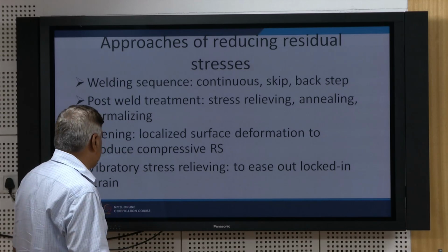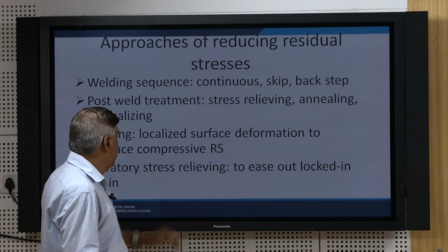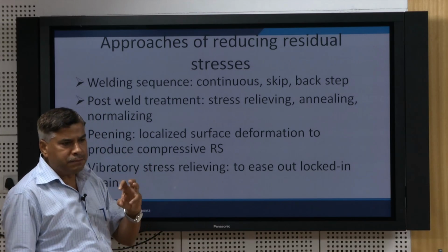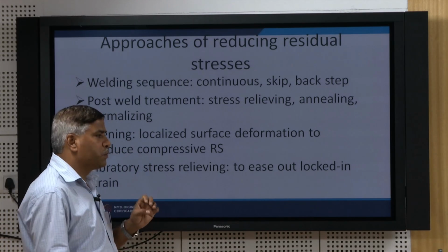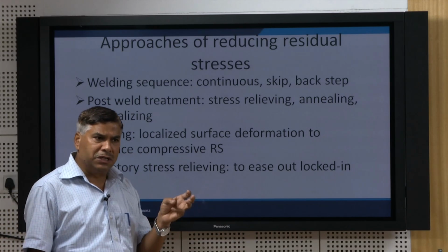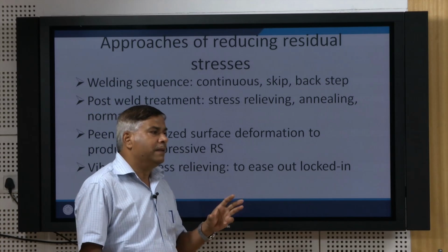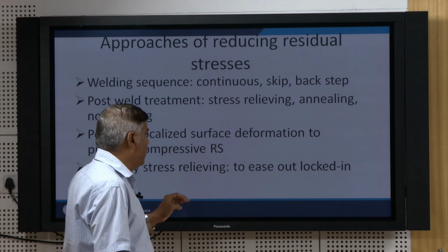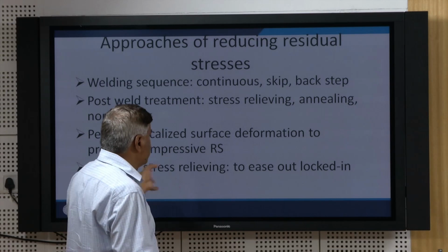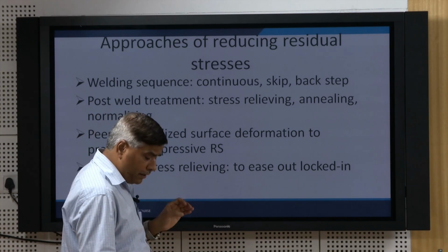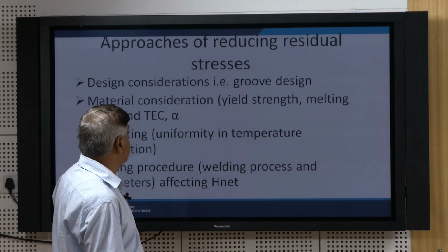residual tensile stresses. In vibratory stress relieving, either in a very localized manner or for the entire part, the part is exposed to vibrations, so that under resonance conditions all locked in strains are relieved, and that in turn helps to reduce the residual stresses.